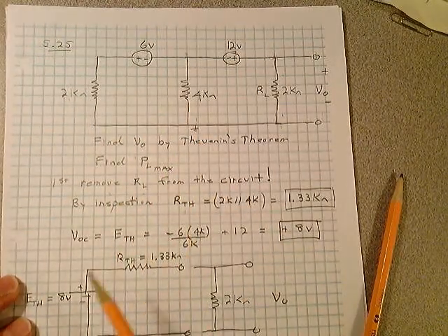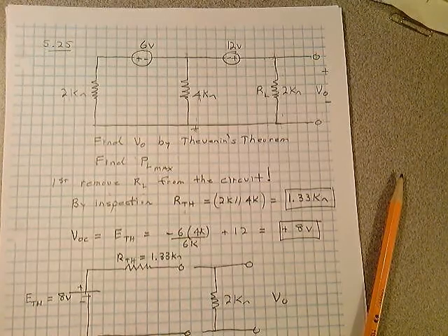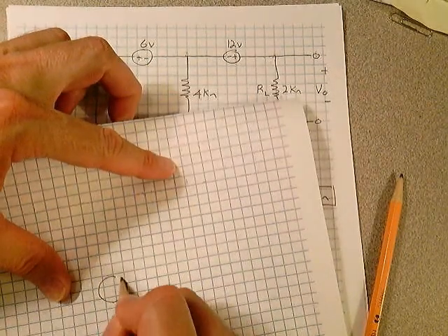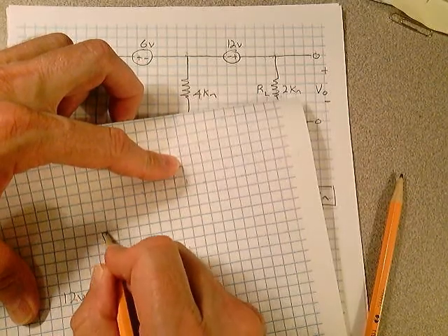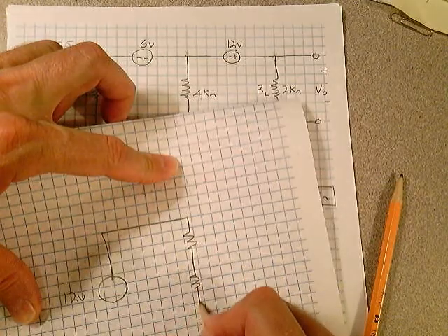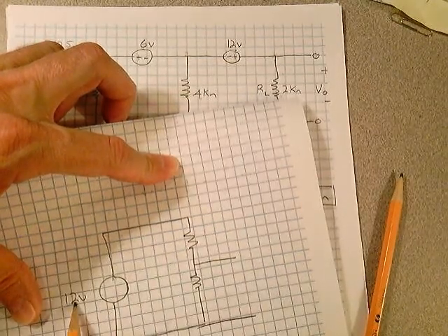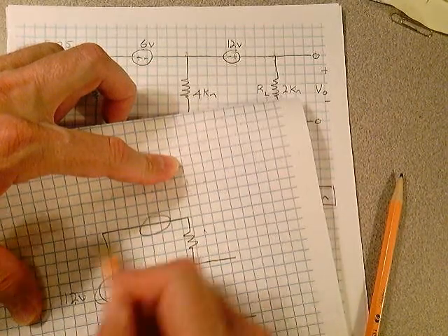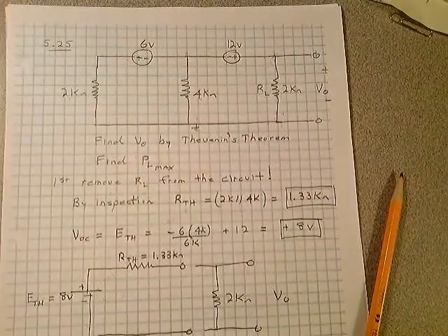Now, you're used to seeing the voltage divider rule nicely written like this. You have a voltage here, which is 12 volts. You come over like this, you come down like this, and they want to know what the voltage is between there and there. It's the total voltage times this resistance divided by the sum of the two. But this can be anywhere in the circuit. These resistors can be anywhere in that circuit, just like they are here.